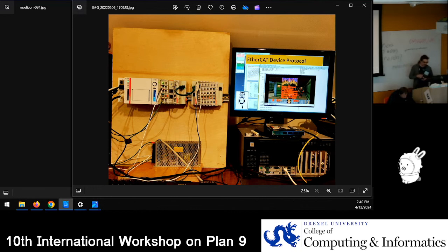And those can be, I'm sorry, this would also include bits as well, which are used to represent coils or relay coils, so to speak, and contacts, as well as just individual discrete inputs, digital inputs and outputs and so on. So to turn a light bulb on, you would turn a bit on. And so Modbus has a few basic function codes built in that provide this functionality. There are a few function codes for reading and writing registers and reading and writing bits.